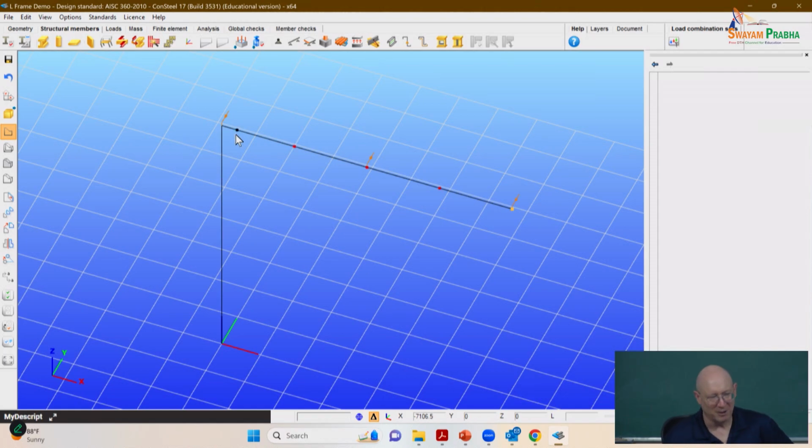Now in metal building design, many metal building manufacturers will design their frame where every purlin and girt location is assumed to be braced on both flanges, with flange diagonals from girts and purlins to the inside flange. Then they have a bracing reduction stage where they come back and ask what flange diagonals can we pull out where it doesn't change the design.